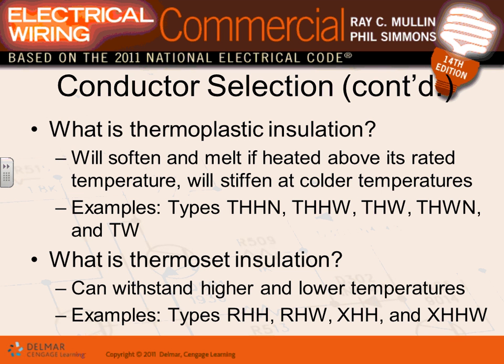But just a few differences between the T for the thermoplastic and the R for the thermoset. The one that has an R is good for higher temperature and lower temperature. The one with the T is good only for higher temperature. It stiffens at cold temperature. So what we're going to be using here inside the building is what type of conductor? THHN. If we go outside, what type of conductor are we going to be using? Any conductor that has a W in it.